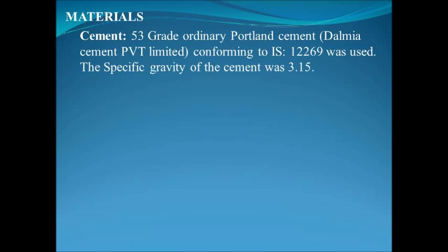Materials: cement, 53 grade ordinary Portland cement conforming to IS 12269 was used. The specific gravity of the cement was 3.15.